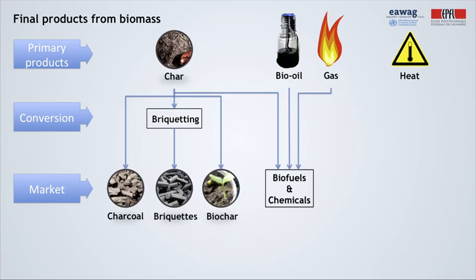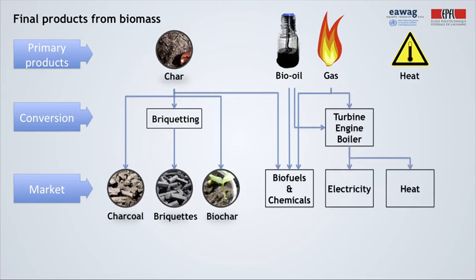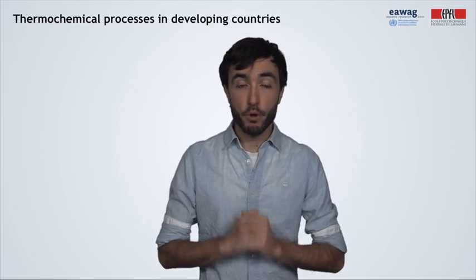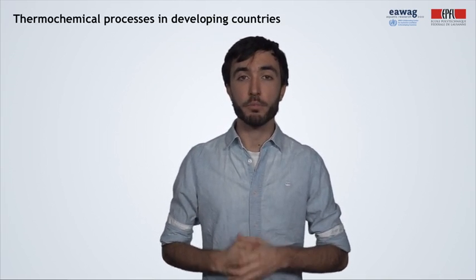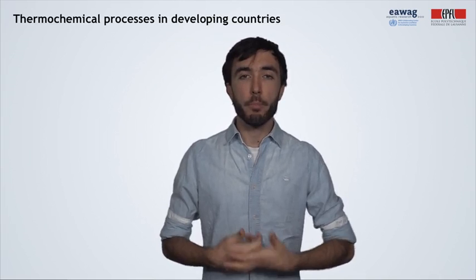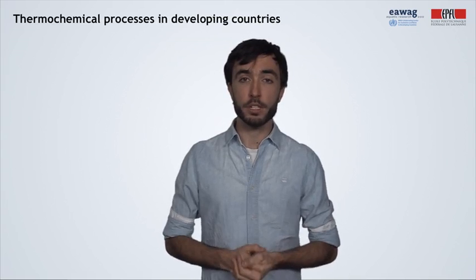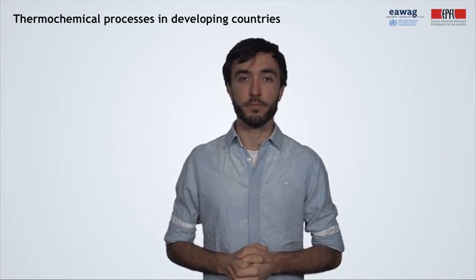Bio-oil and fuel gases can be upgraded through refinery in order to synthesize other chemical compounds or to be used as biofuels. They could also be consumed in turbines, engines, or boilers and produce electricity and heat. The heat obtained from combustion can be used in boilers to obtain electricity or directly commercialized. Thermochemical conversions are therefore promising considering the growing challenge of waste disposal and dwindling fossil fuels. Being aware that biomass represents the biggest waste fraction in developing countries, these processes might represent opportunities to valorize it.